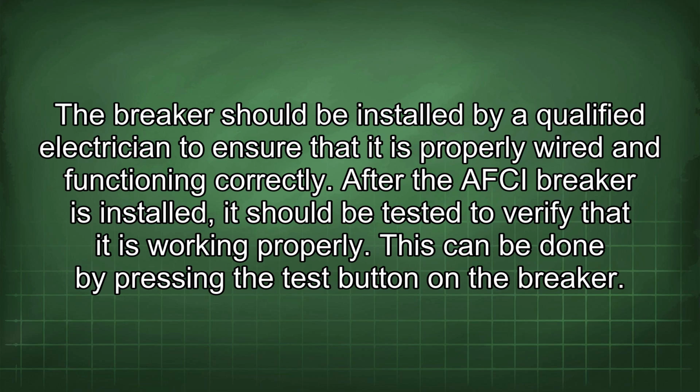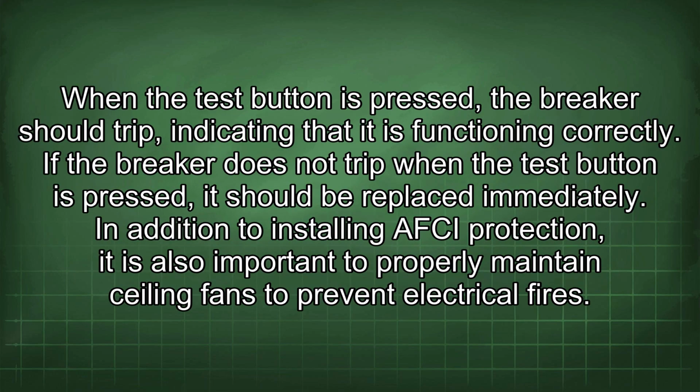After the AFCI breaker is installed, it should be tested to verify that it is working properly. This can be done by pressing the test button on the breaker. When the test button is pressed, the breaker should trip, indicating that it is functioning correctly. If the breaker does not trip when the test button is pressed, it should be replaced immediately.